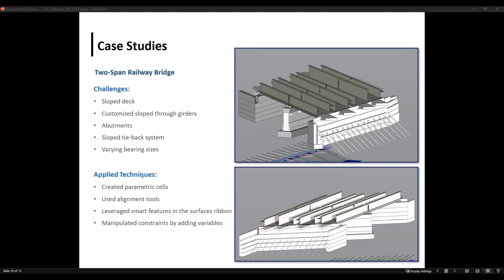In this case, I also remember that I used civil alignment tools to follow the correct curved slope for the deck. On top of that, I had to generate different deck levels to position the framing right in space and, of course, accurately.